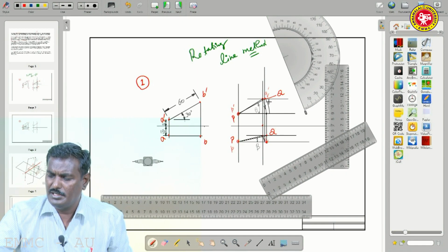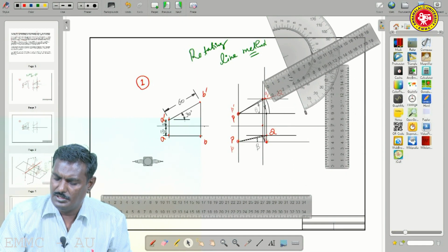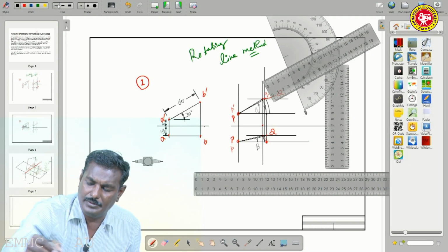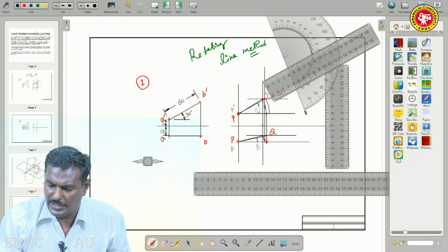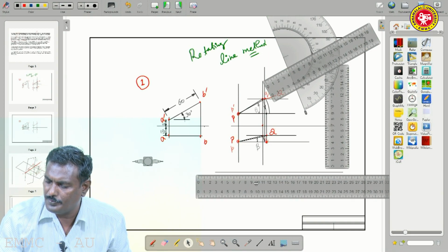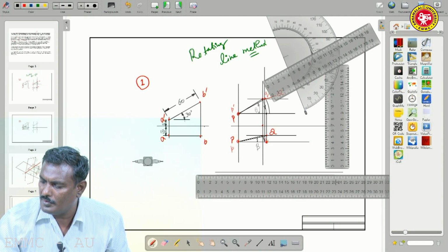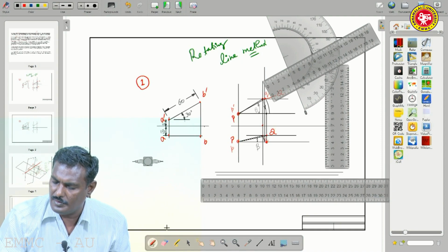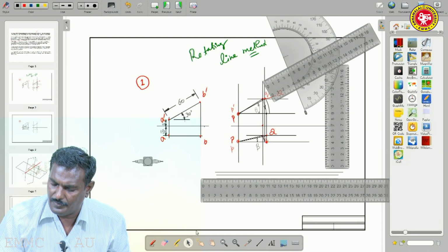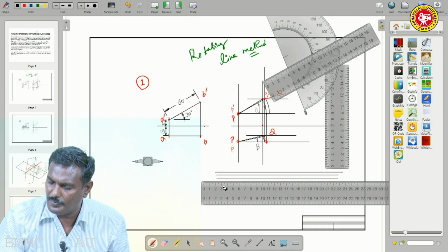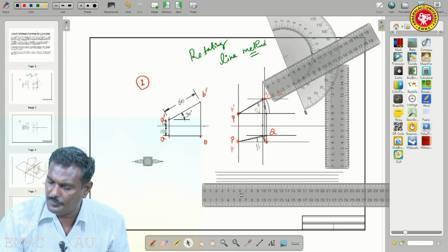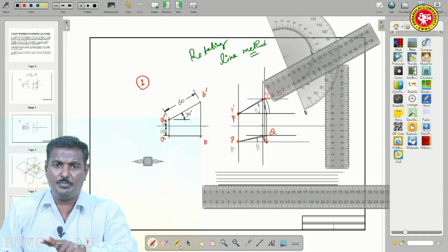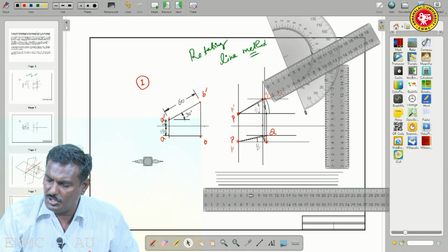So, you have to write it by using this, you have to print. So, draw a guideline. Draw a guideline for approximately 6 mm. Approximately 6 mm, draw a guideline. So, here we have to write it. Draw a guideline. Why do I do it in 3? Because inclination with respect to HP, inclination with respect to VP, true length. For that only draw 3 guidelines.